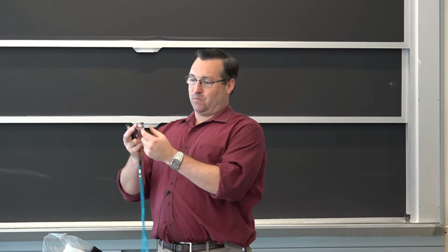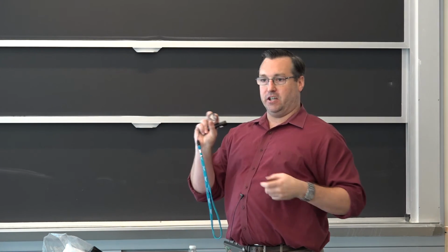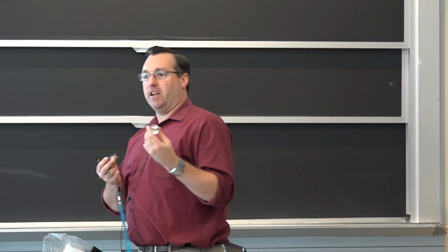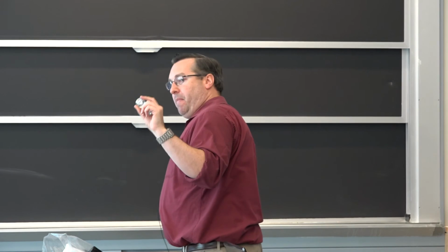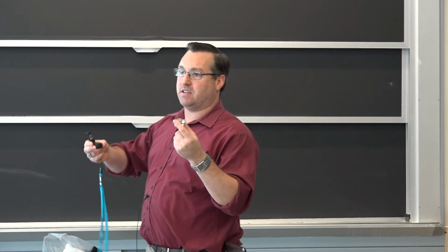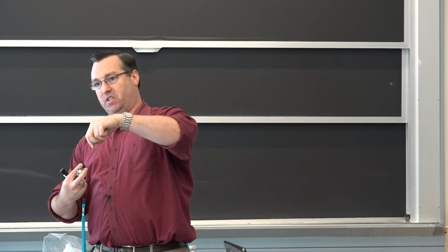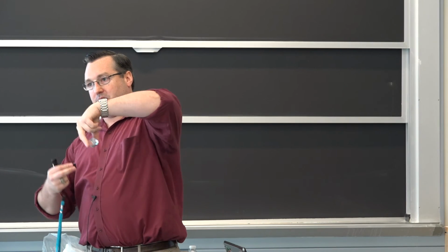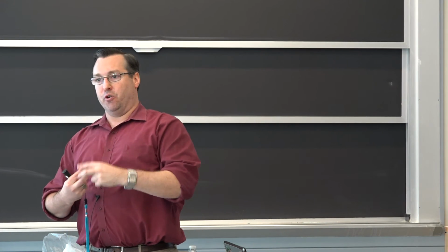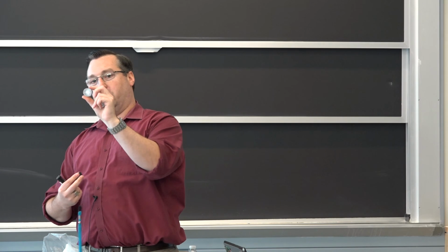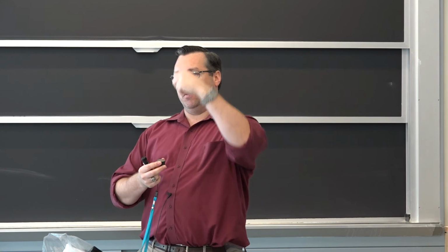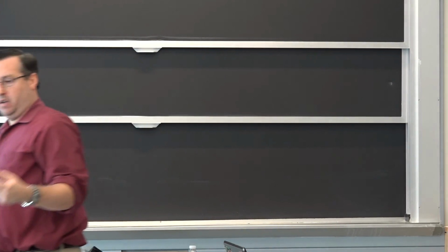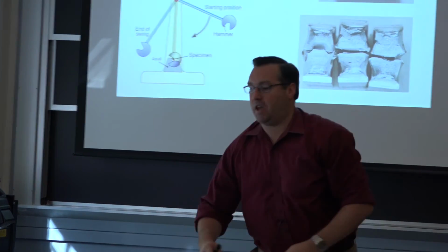So if you see, there's a huge cloudy area in here. You have to mix the stuff right and you let it set. These are cold mounts, which are epoxy based. So you'd put your material in flat, you'd mix this two component goo and let it sit for 4 hours. You get a clear mount, or you can do a hot mount where you do it under temperature. So these are various mounts from samples.